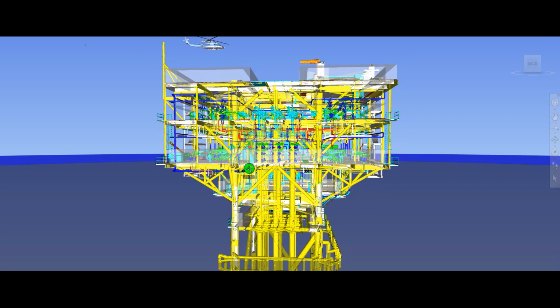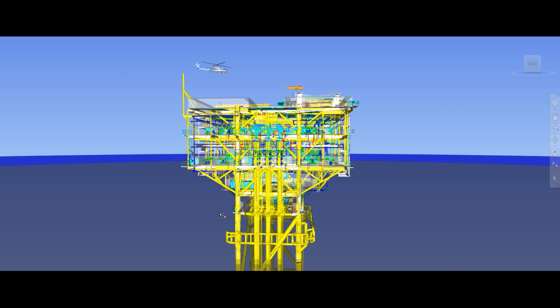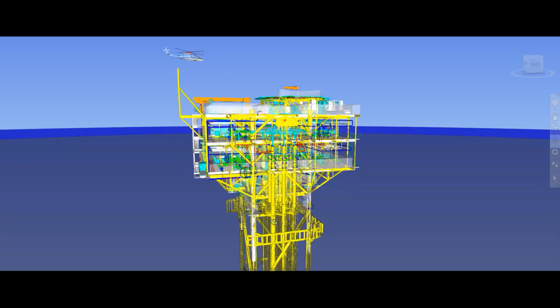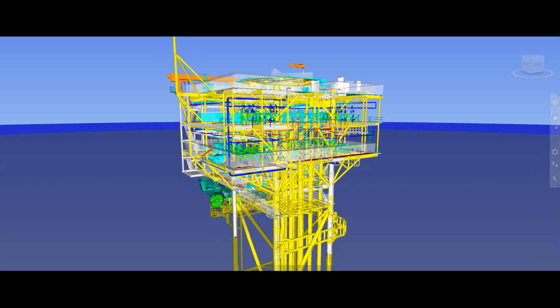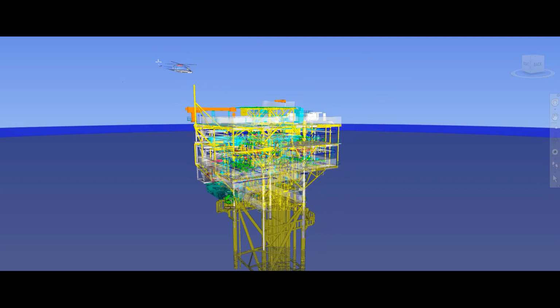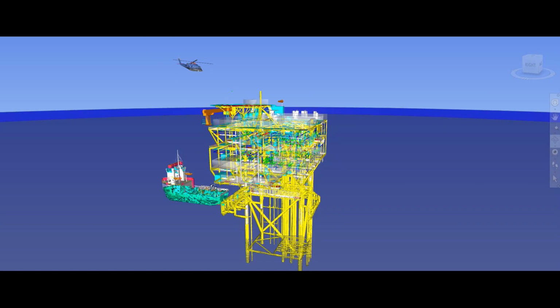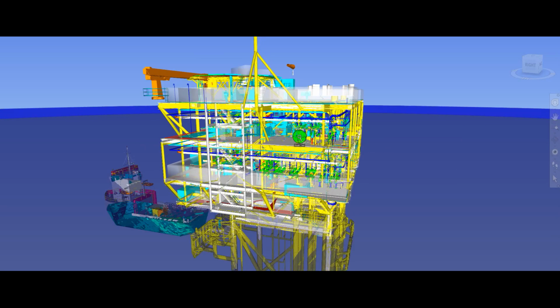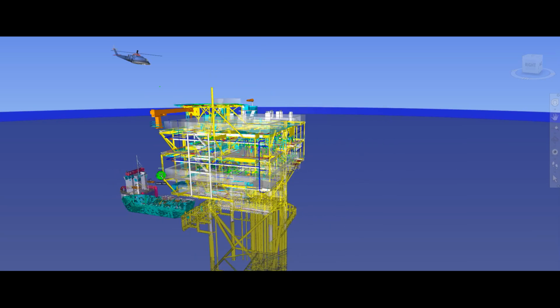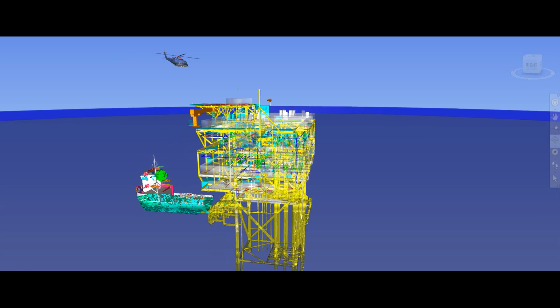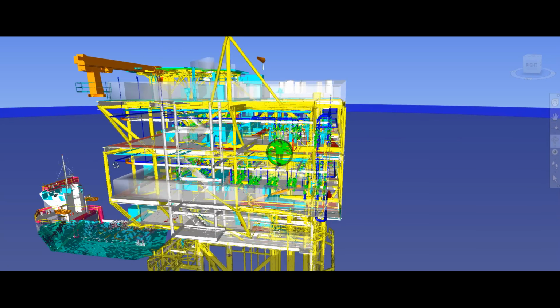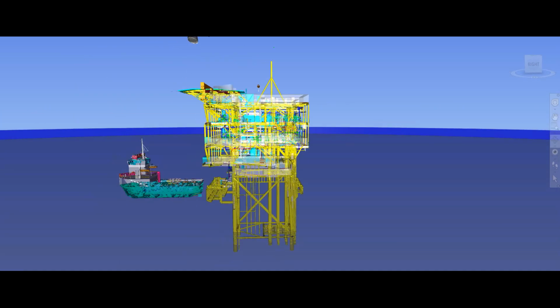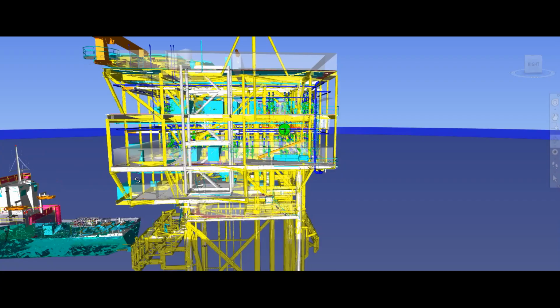All the wellhead platforms have a boat landing, a cellar deck, a jacket walkway, the main deck, mezzanine deck, then heli deck, and the equipment that we already discussed, like the Christmas trees, and then choke valves, and then we have the 3 headers, production header, test header, and the drain header, and each is connected with its own. And then we have J tubes, and those are for the electrical instrumentation.